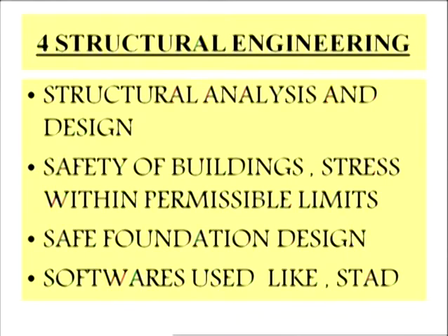To make a structure safe against all the external forces like the wind forces, earthquake forces, live load, and the different types of the loads which are acting on that building or a structure. At the same time, the foundation which is required to be designed must also be safe. So for that purpose, soil investigation is to be carried out and the safe bearing capacity of a particular soil is to be measured so that on the basis of that a safe foundation can be designed.